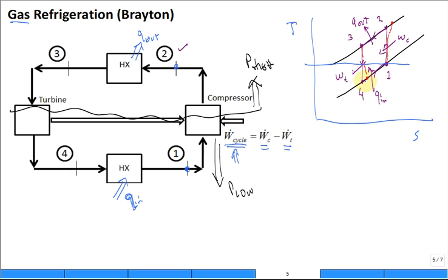It looks easy to bring it in right after here in the early stages of that heat exchanger when the temperature is 4, but as it's going through the heat exchanger, it's warming up and getting hotter and hotter. Now it's temperature 1. So what you're cooling has to be at least this temperature. The low temperature can't be below T1. Does that make sense? It can't be below T1.